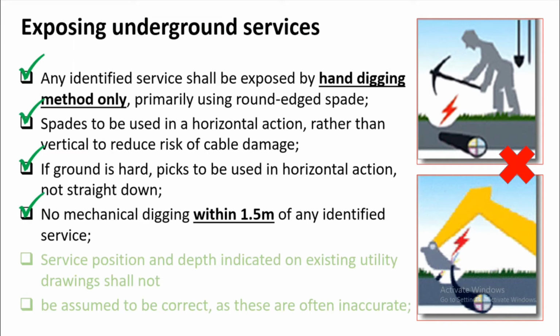No mechanical digging within 1.5 meters of any identified services. So within 1.5 meters of any identified services, avoid mechanical digging. As much as possible, you must use only hand digging to expose these underground services.